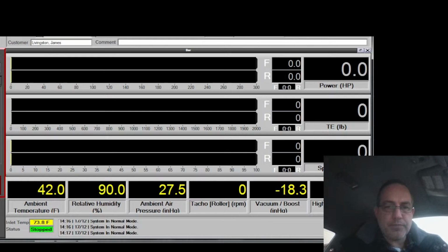Alright, let's see. So I've got a 12% fuel trim at idle. Now some of that I believe is going to be the change in map sensor, and some of that could be the fact that now it has 2 fuel pumps. Differential fuel pressure is a smidge higher than it was before, but only a tiny bit. And my VE at idle. Sorry for clearing my throat.